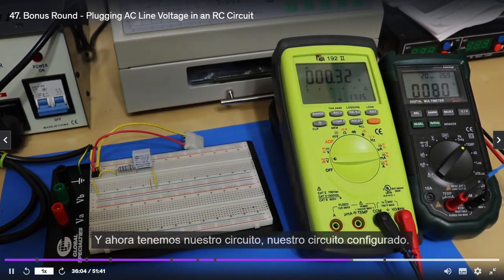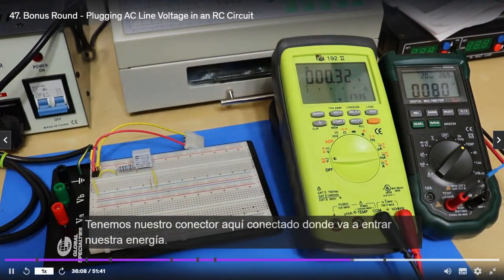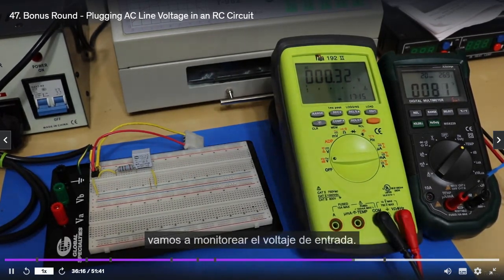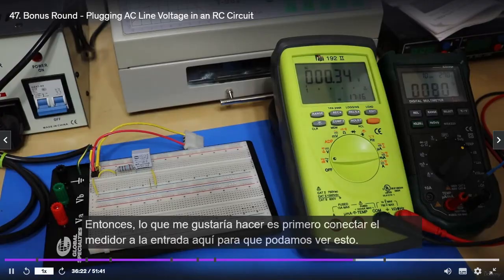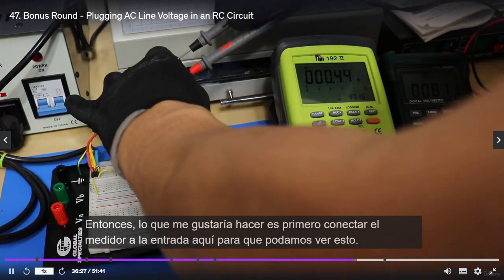All right, and so now we've got our circuit set up. We've got our connector here connected where our power is going to come in. So now we're going to turn this whole thing on, and we're going to turn it on slow and monitor the input voltage. First, let's connect the meter to the input here so we can watch this.